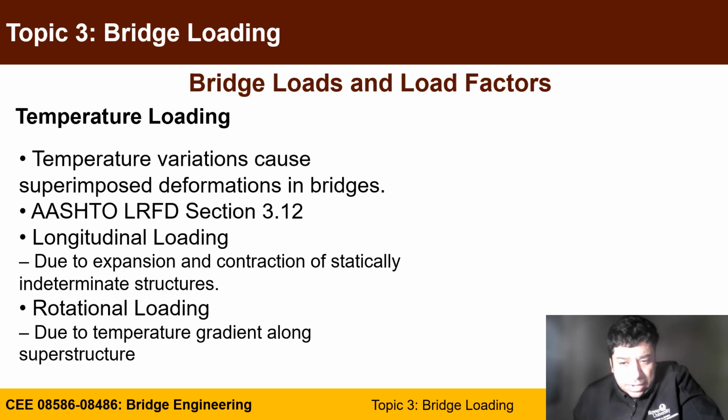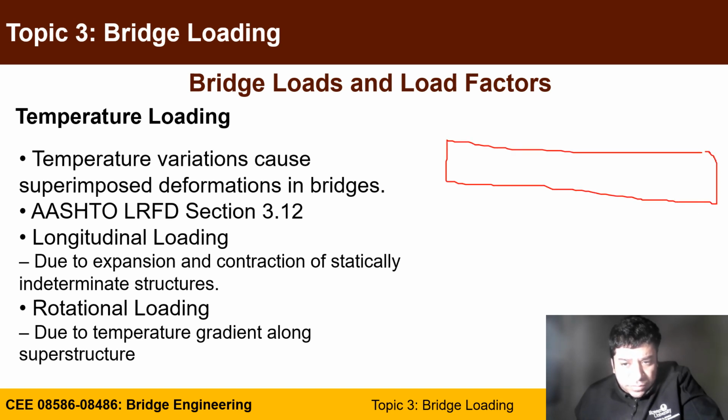So as I described earlier, you have a big steel girder of, let's say, 150 feet span. If you have high temperatures, they are expanding. If you are allowing the deformation, nothing will happen. If you are locking the deformation, so you do not allow lateral deformation, they impose axial loading on your structure.